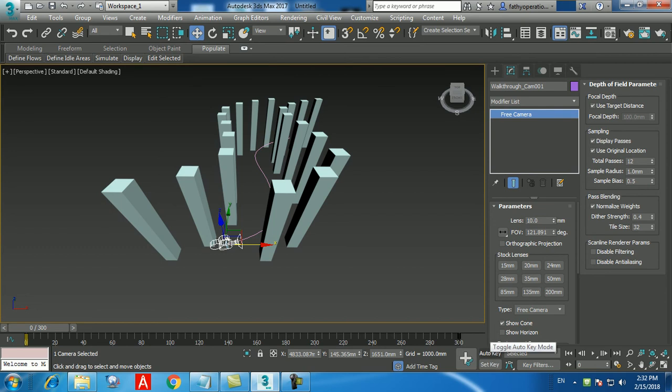what you're going to do is, this time we already tried auto key. Let's try set key. So click on the set key. Now as you can see, this is the animation. That's my camera going around, right? So I'm going to click here on the key to say that, for example, the animation is starting from here. So I will click on the key like that.